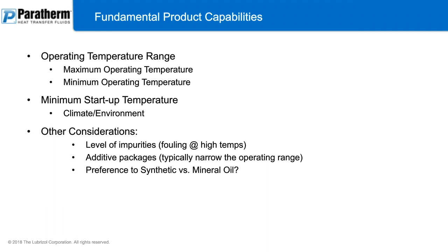Another product capability inherent to the product you're looking at is the presence of an additive package. Additive packages sound nice. They often get applied as extra protection against some kind of degradation mechanism that you're looking to avoid. But be really careful with those claims, because typically when you have a higher treat rate of additive packages being advertised and touted, they're going to narrow the operating range and capability, and eventually the lifespan of the fluid you're looking at.